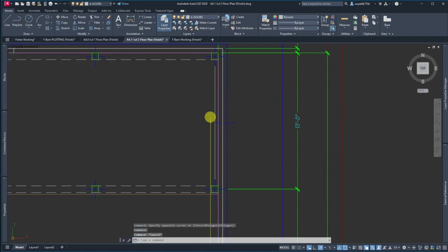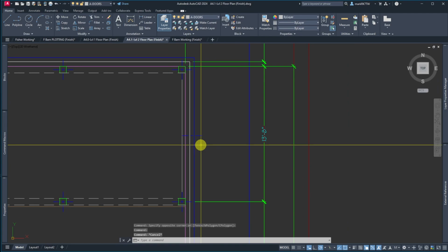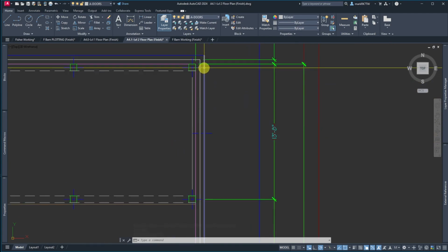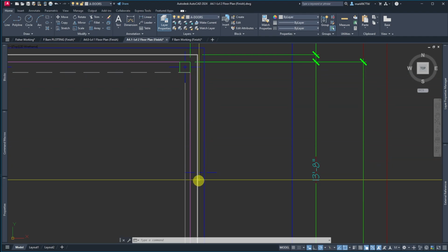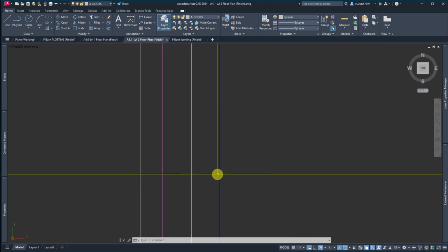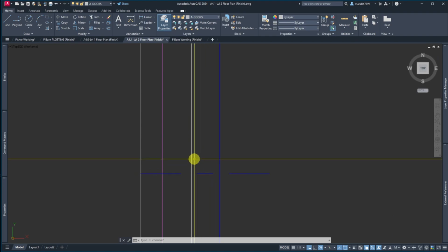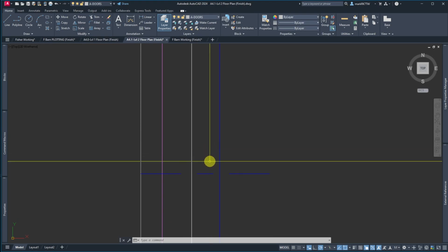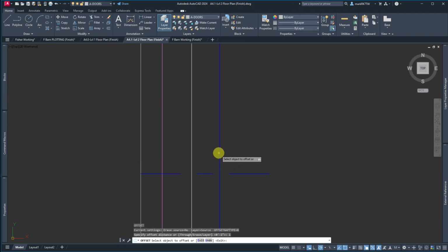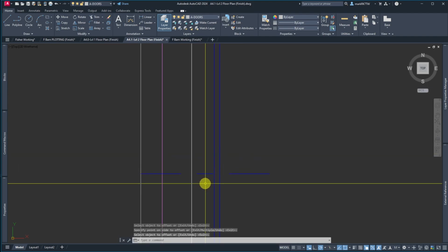If you make a 4-foot line, then it can be 24, but I used 2 foot for this part. This is my framed wall. And this is my timber frame. We're putting the window in the framed wall portion. It'll probably get pushed to the outside into the insulated portion. So if we consider it in the insulated portion as far as where we're going to frame it, it's going to go 1 inch back from here so that it sits on the furring. And you'd have to go back to further lesson plans if you really want to understand that.